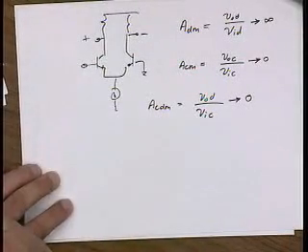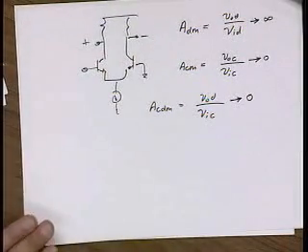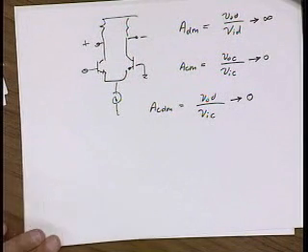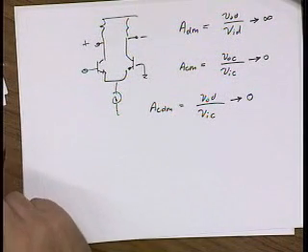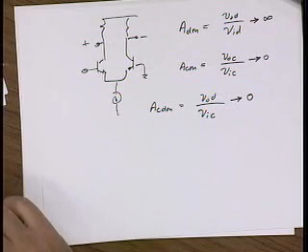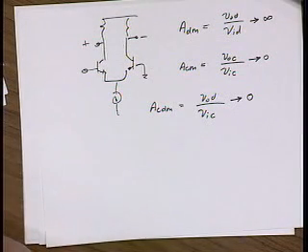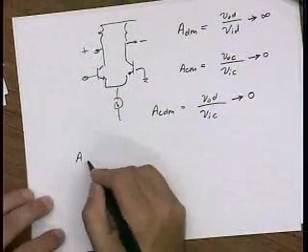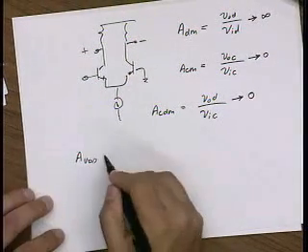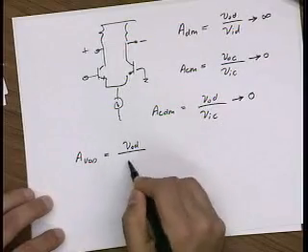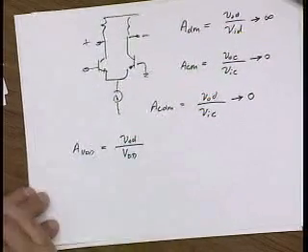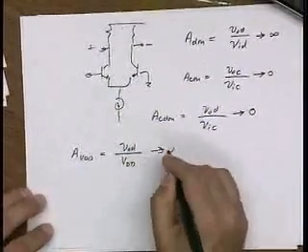Okay. What else is important in a fully differential amplifier? Any other useful gains? Matthew? Power supply rejection. Yeah, very good. So I want the gain from VDD, which is the differential output signal for a small signal excitation on VDD, to be 0, right?